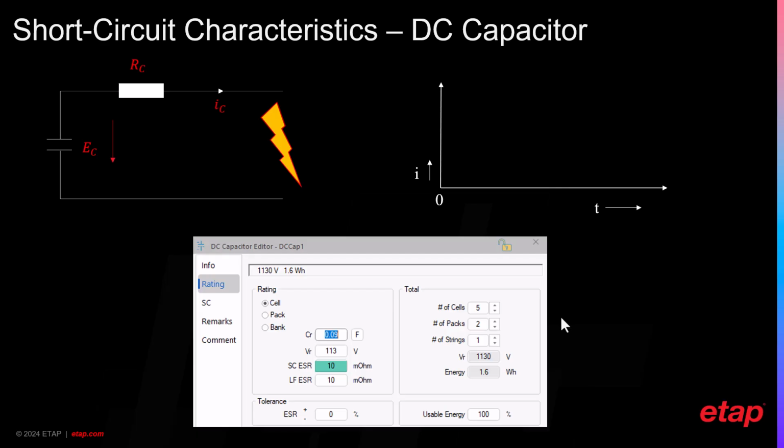And the current to time relationship based on the resistance and the charging current can be calculated by the standard, and it is also simulated in ETAP based on the peak charging time and the peak current associated with it. This current, together with the battery current, would give us the most updated profile of the short circuit at a given fault location.